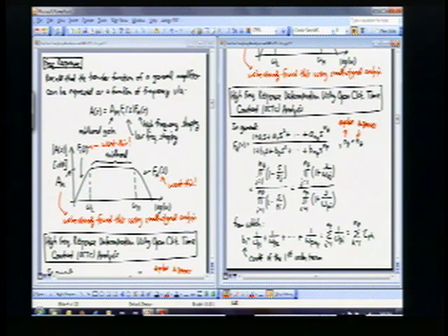All right, now I could also say that if I have all these factors based on these poles and zeros, if I focus just on the poles, which is all that's important for me right now, later on we'll address those zeros, but much later in the class, because they will have an effect actually. But for now, just looking at the poles, this B1 coefficient in this f sub h, just through math, I can tell that it's going to be equal to the sum of all these pole locations, omega pi's here. So just through the math of all this, that's the way that this works out.